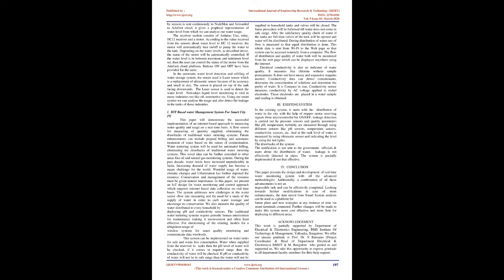Presented here is a water management system using IoT. Water level indication, automatic water pump on/off, etc. are carried out by this project. The laser sensor used in this project is the VL53L0X for precise level indication. The issue of water scarcity is becoming more prevalent. IoT-enabled water management solutions like this use sensors to collect data and share it to the cloud.